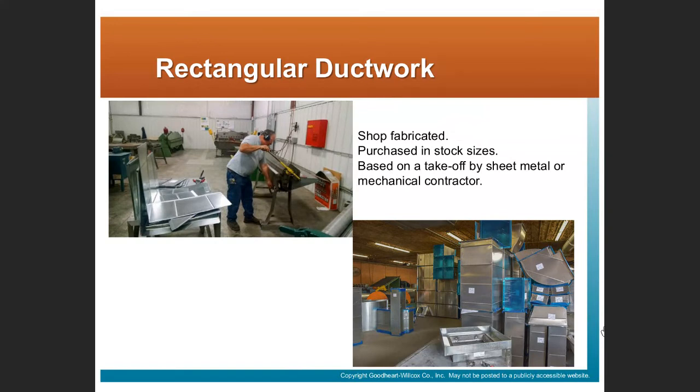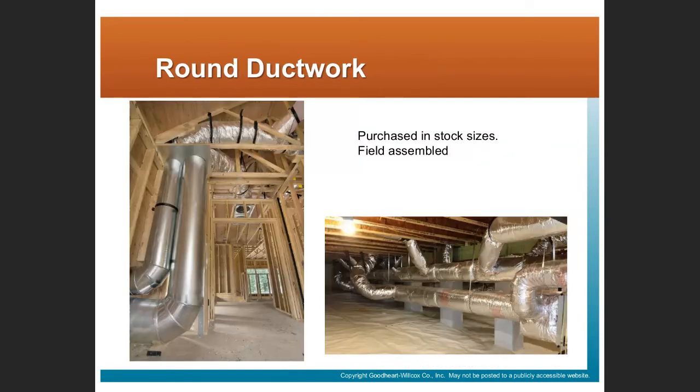Again, the ductwork is fabricated, it's tagged, and in this case, you see they've protected that ductwork so it doesn't get dirt or moisture in it. And they load all this on the truck and it gets trucked out to the job site. And again, the tinners, the sheet metal tradespeople, put that stuff together. Again, we can do the same thing with round ductwork. So purchased in stock sizes, assembled in the field.